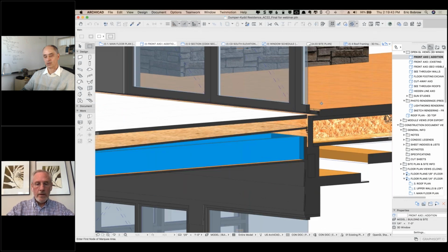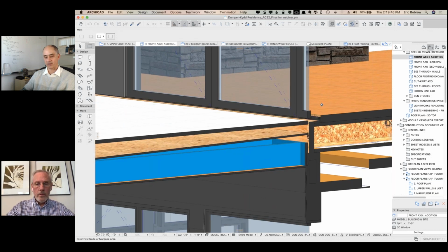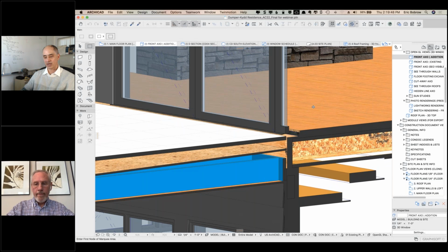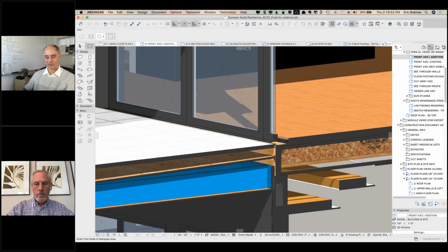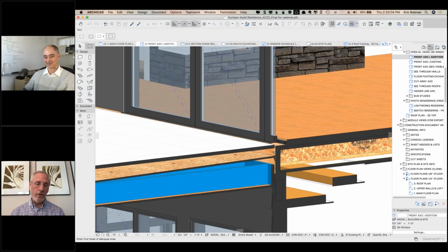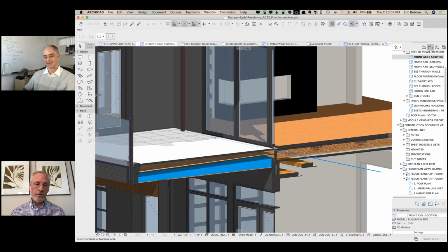But so you're doing all of the framing here in 3D. I can see the TJI and these other framing members. So you said this was a very satisfying detail, but an expensive one to create. It is expensive. Well, you're basically building two patios because you have to have a roof membrane on your framing, and then you're supporting a whole other one. In this case, I think they used 24-inch square granite pavers, and then they're all supported.